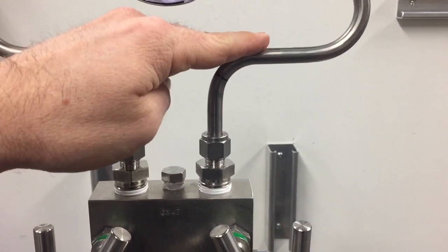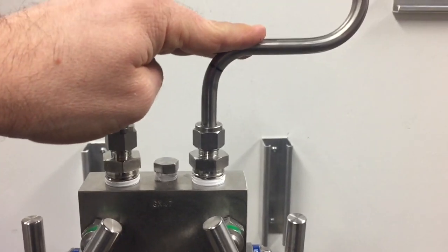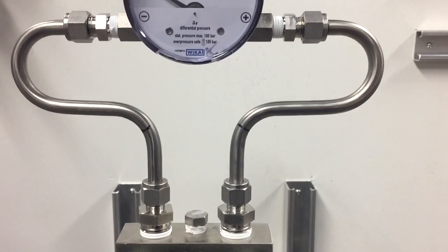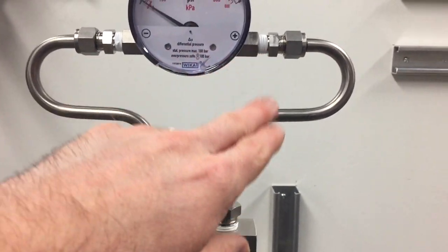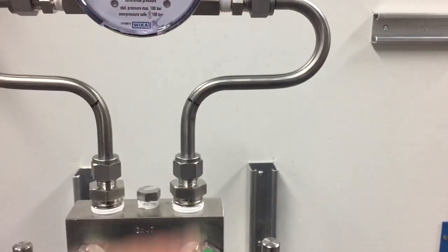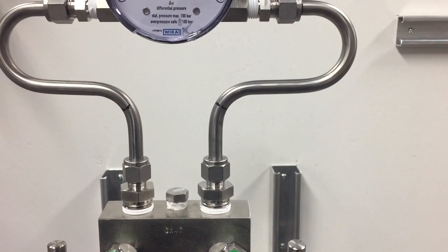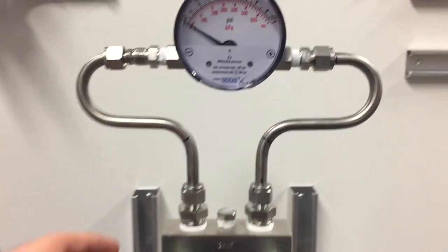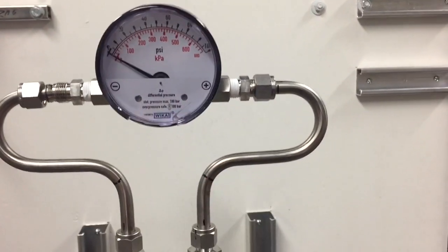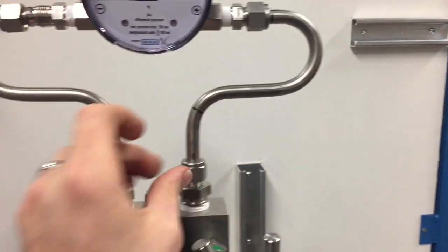But you want to make sure that this is all the way down into the fitting before we tighten up and do our 1 1/4 turns on our nut. So I'm going to take this gauge out and do each one of these individually, just to make sure that they're all pushed down and set properly. Alright, so I've set all these now. I've done 1 1/4 turns on all these nuts, and I was able to hand thread all of these nuts back on except for this one here.